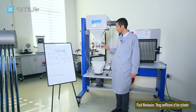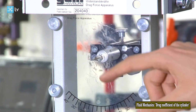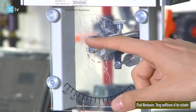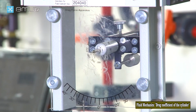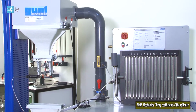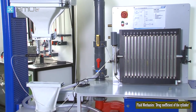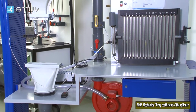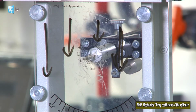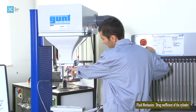Okay, and also before starting the experiment, you can see the cylinder setup is in equilibrium. It is not under any force. If I apply a force and remove it, it goes back to the equilibrium condition. It is in equilibrium at the beginning of the experiment. But when there is flow, the flow goes from that tube and then to this nozzle here, it increases the velocity, and from that nozzle it acts on this cylinder. So if I put some velocity acting on it, you can see that the position of the cylinder changes because the air acts on it with some force.